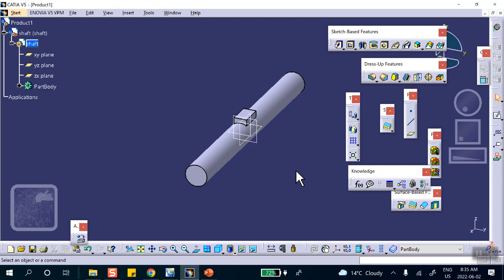So what you need to do is put your load on a particular area, a patch, and that you have to create. You need a feature to put your load on. This feature can be something like that, or it can be a surface on that shaft that I have created, and you proceed along that line. Okay, so I'll just leave it like this.